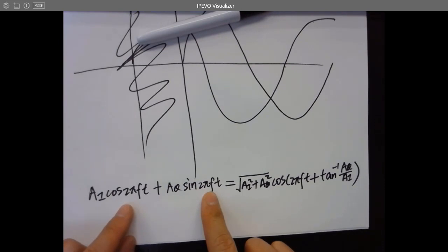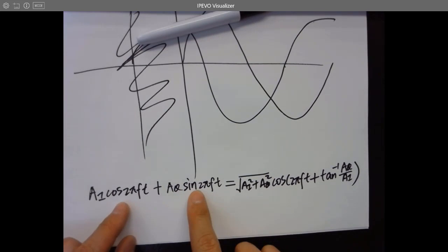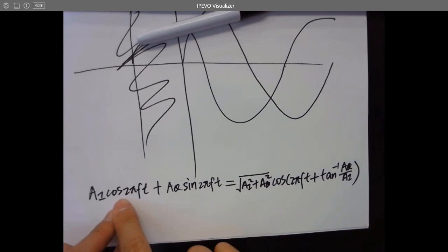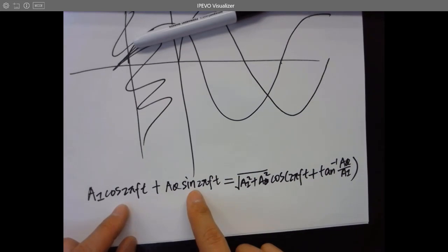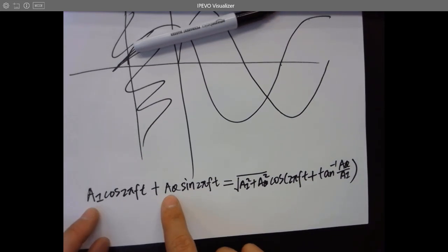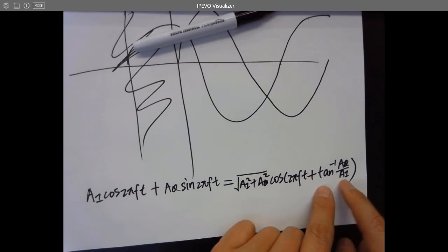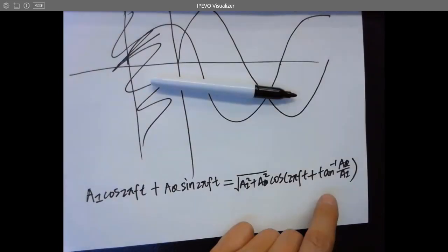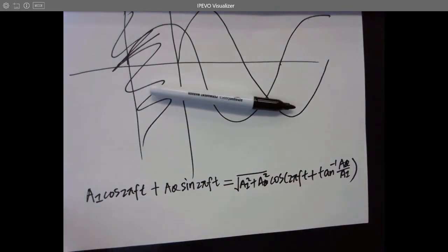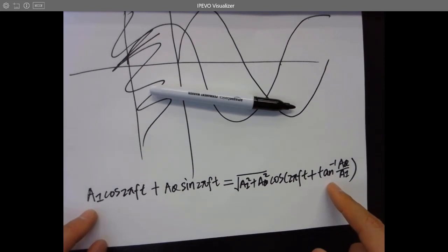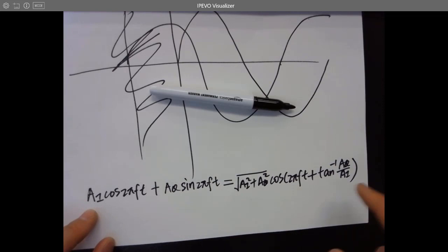No, you are not. Sine wave, cosine wave, 90-degree phase shift. In phase, out of phase. 90-degree out of phase. You're only changing AI and AQ. See? You got a phase shift. It depends on AQ and AI, the ratio between these 2 numbers. So that's why you are looking at the third sine wave in LT-SPICE. When you are changing these 2 numbers, you are seeing a change in phase and also amplitude, right?